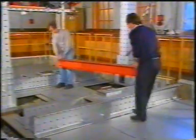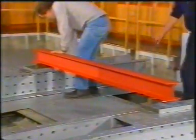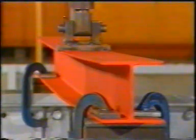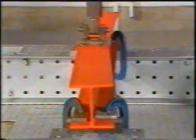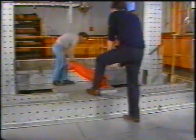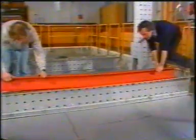The third beam of this series of tests is just over 2 meters in length, and is neither very stocky nor slender. The beam is subject to load as before. It can be seen that lateral deformation and twisting occur, together with plasticity. Removal of the load is accompanied by only partial recovery of deflection, and significant permanent bending remains in both principal planes.